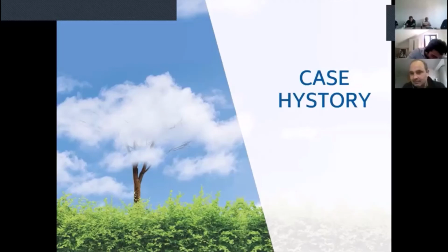That is the most important thing. Not wrong, yes. This means that in the first period of the working time, the pressure drop will be lower and the performance will be higher than the design. And when the cartridges reach their nominal pressure drop close to 800 Pascal, you will have the good performance. So it's a good way to design the filtration system.